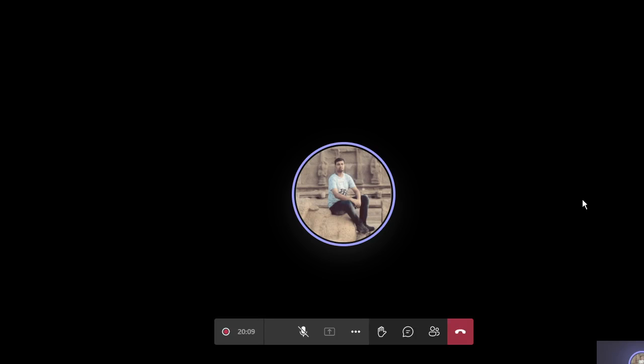What else will happen with that? The read/write bar signal is activated. If you want to read, you have to activate the read signal. If you want to write, you have to activate the write signal. Here you have this data transmit/receive signal, which will be changed accordingly, depending on whether you want to transmit the data or receive the data from this transceiver. Correspondingly, you have this read bar and write bar signal here. This signal will be activated, either read or write bar, because we know the address of.